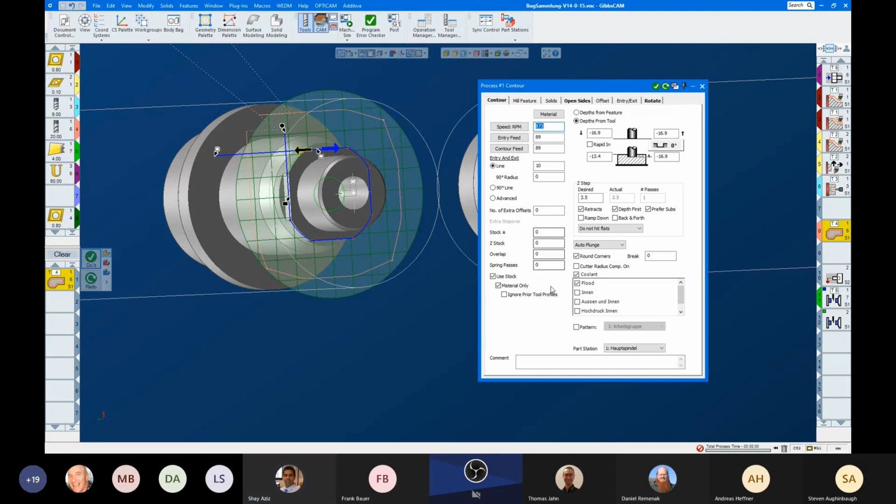Yeah, but that's what I wanted. That's exactly what I wanted. I wanted it to stop where the material is not, but I didn't want it to wrap it along the already machined face. Okay. Because if you turn off material only, it'll also move along the radius. Right. This is what I wanted to avoid. Well, we'll get this assigned and we'll get it turned in, give it to Daniel or whoever, and they can dig into it and get you an answer.